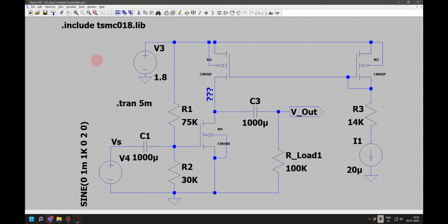Oh, okay. Yeah, analog. It doesn't matter. See, PMOS has a slightly greater R0, but for the same current you might have to use a slightly larger transistor because of mu P being lower than mu N. So that might affect the